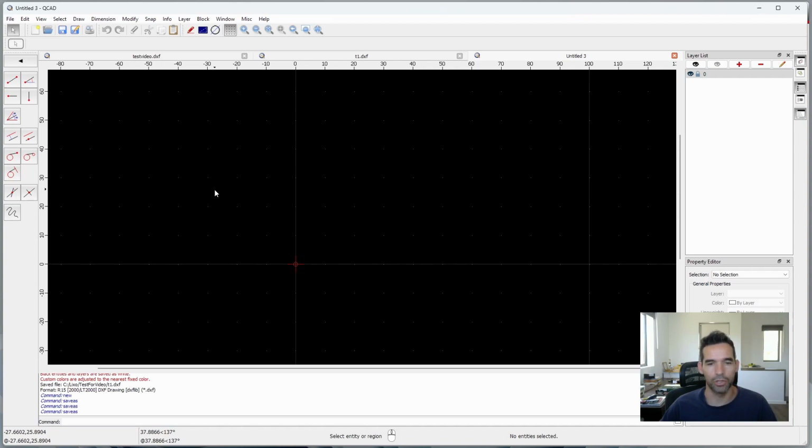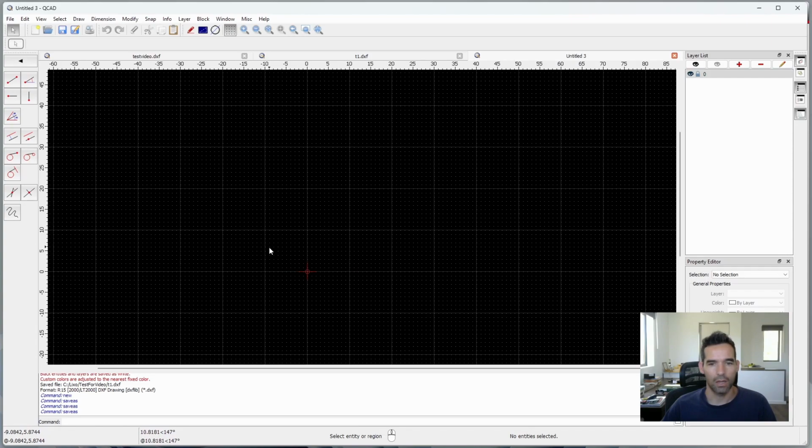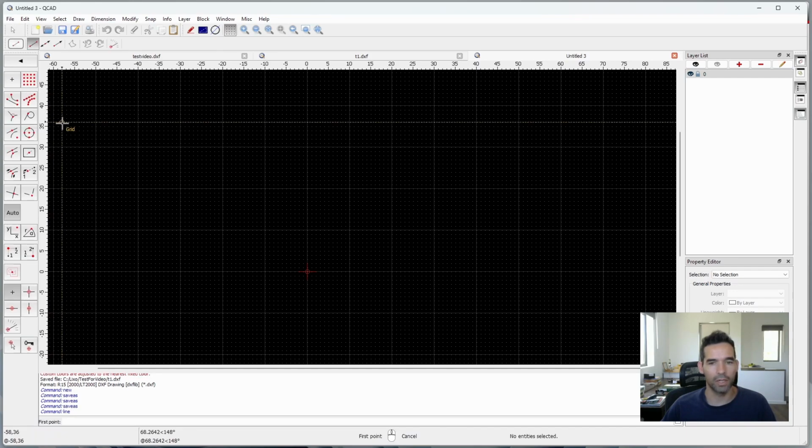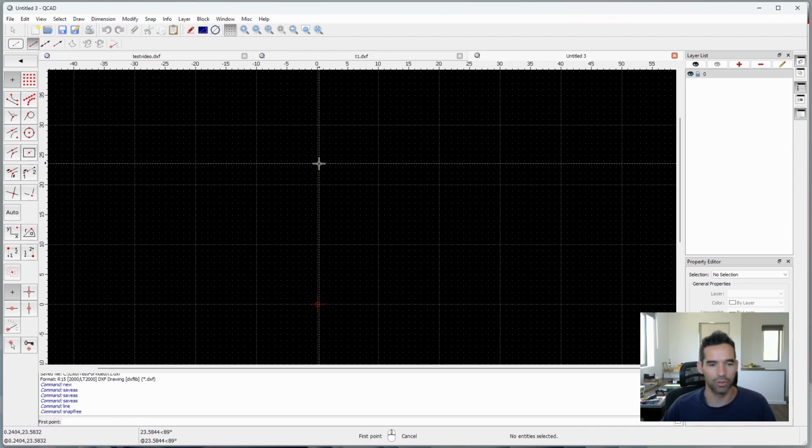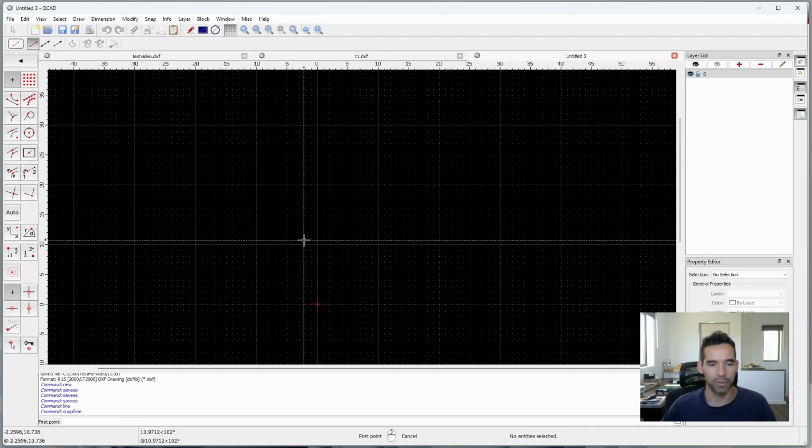As your machine uses coordinates, we will use the coordinate system of the CAD to draw the exact part that we want. As a basic rule, we should start from Z0, that is this line, to the negative space, and we are drawing in radius. So if I want a part with 100 millimeters inside, I should draw 50 millimeters.